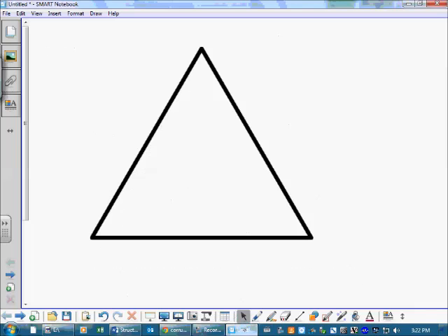Okay, now triangles. Let's take a look at triangles. Now, just pause for a second here again and think of why a triangle is so stable. Okay, number one is they have a very wide base. And a wide base means wherever that center of mass, center of gravity, wherever it is, if it's got a wide base, it has a much better chance of the center of mass being in between these 2 points somewhere, right? So the wider the base is, you increase the stability of that structure.